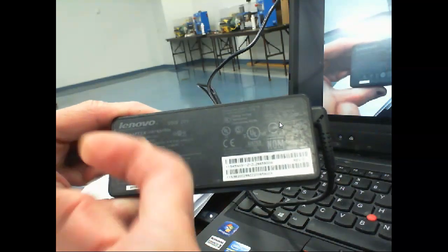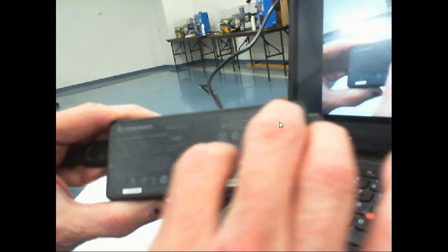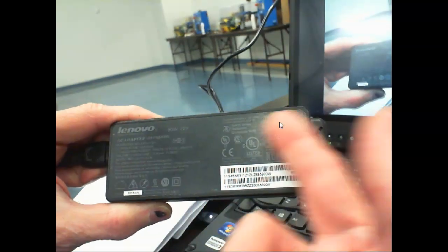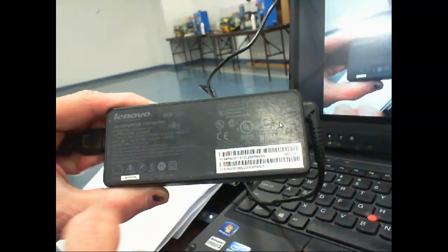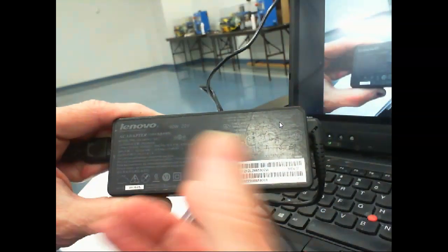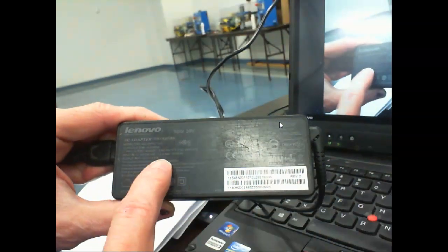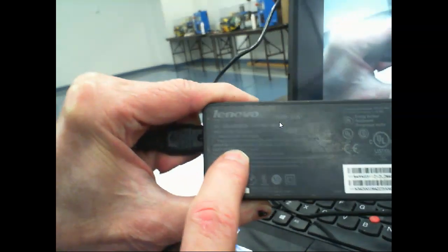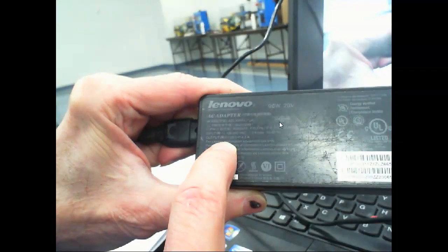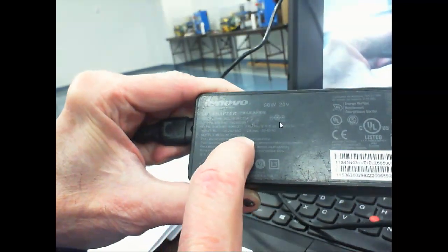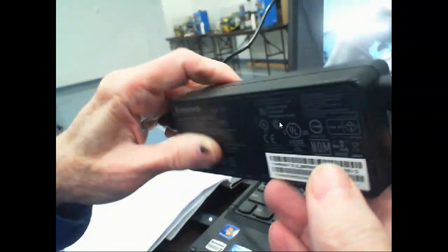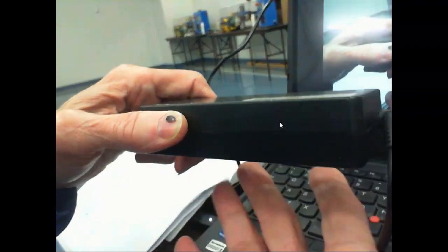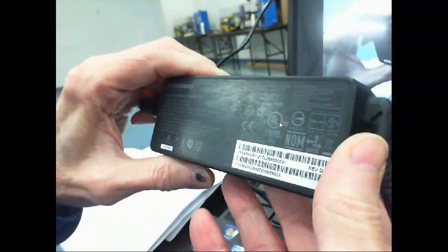So when we went over to Germany, all we had to do was buy the adapter that adapts the U.S. plugs over to the German plugs, which are weird. They're round-looking things, and we had no problem charging our computers because of the wide range of this switching power supply. If this was a linear power supply, there's no way in the world, if y'all can see that, I don't think you can, that it could do that. So 20 volts at 4.5 amps, and that's the size of it, but it's all sealed up and epoxied. If I took this thing apart, there's no way in the world I could fix it anyway.